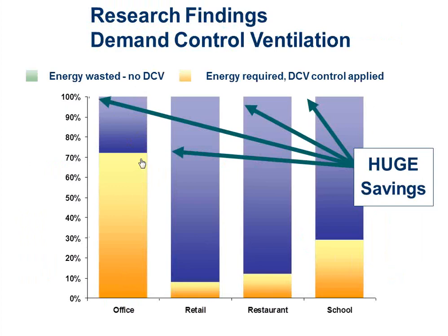High-rise condo buildings are a different discussion. Even though you're talking about the common areas, you probably can't do any CO2-based demand control ventilation in those condo buildings because the common areas typically are handled with some kind of makeup air unit that's pressurizing the lobby and the hallways, and that air is expected to pressurize those hallways and then leak under the doors into the condo units and then get sucked out the individual bathroom exhaust fans. So since you really can't track what's going on with the individual people in the spaces, this is really not applicable to residential, even residential high-rise, which is similar to commercial. But for office buildings, absolutely yes, similar to this data over here.